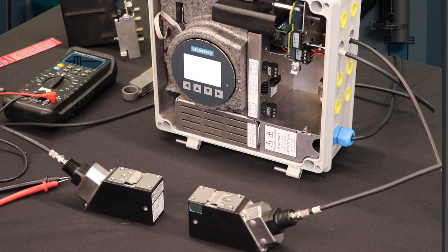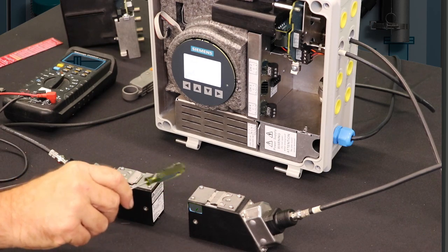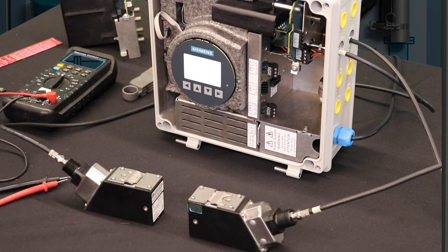So as an example, if these two sensors were mounted on a pipe which was 4 inches in diameter, what you would do is reprogram the meter at 2 inches in diameter and switch from reflect to direct 1 traverse, and then look for the signal.